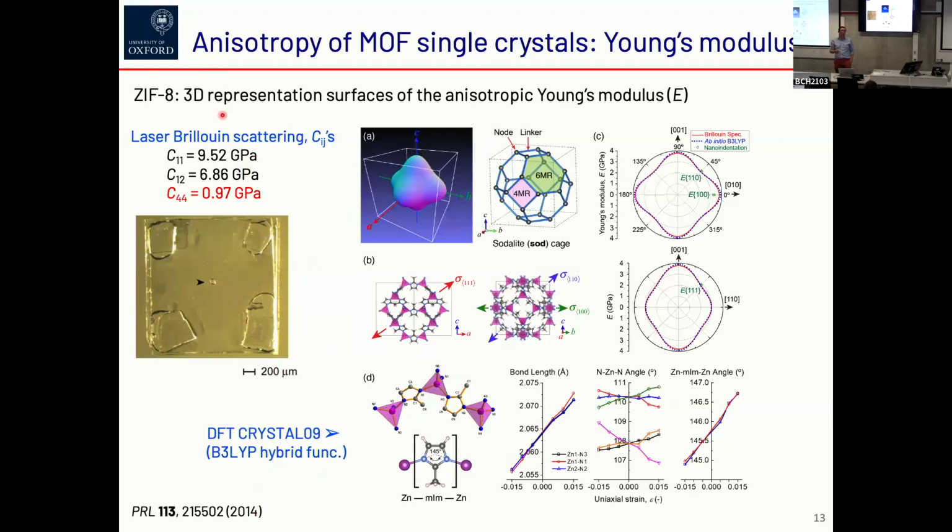So the idea is to extract these elastic constants from a slice of this crystal, and being cubic, there are 3 independent elastic constants. So C11, C12 for axial shear coupling, and shear C44.